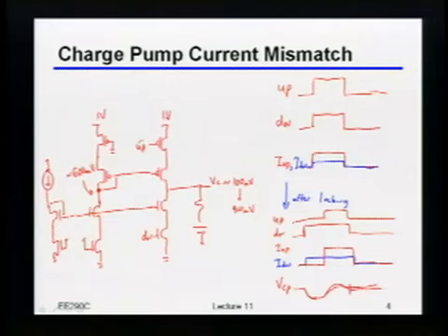But if I keep repeating this every single cycle, then I'll see a reference spur because every n cycles, I'll get some cycle that's long and then short and long and then short. For example, let's say I do a divide by 10. On the reference cycle, I maybe get a short cycle and then 9 long cycles, and then short, 9 long, and so on and so forth, right?